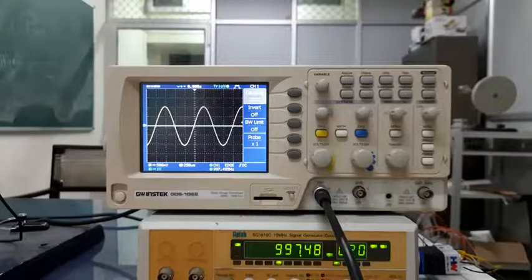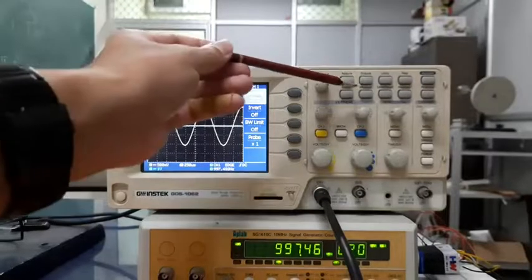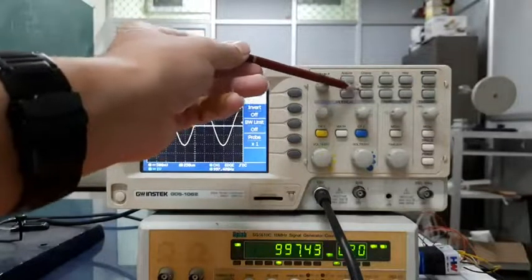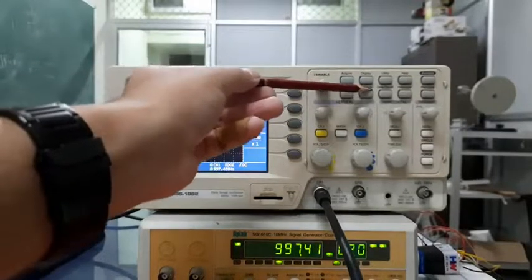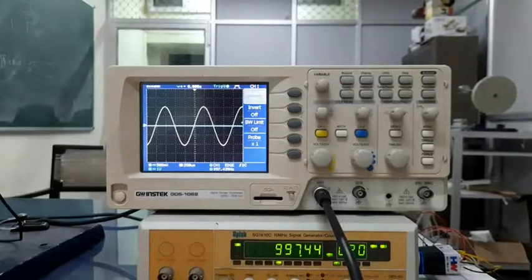a more advanced feature built in. There is a button here which says measure, right? And of course its location can be different depending on the model, but there will always be a measure button here. So by using this, one can actually make more quantitative measurements. So these are internal measurements done by the oscilloscope and shown to you so that you can take the values correctly, right? So this will come again when we perform an actual experiment, but you are welcome to now try out different modes of this oscilloscope, right?